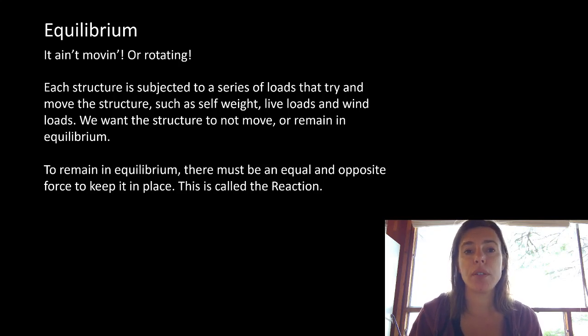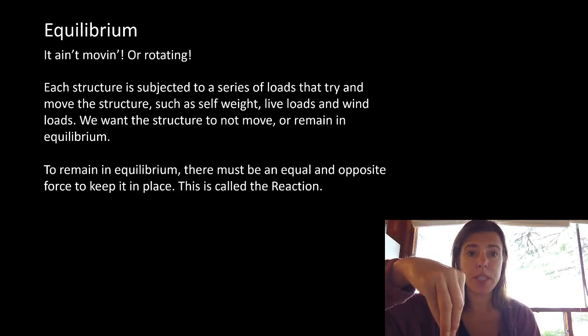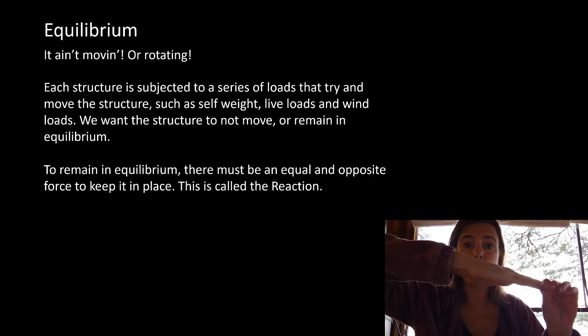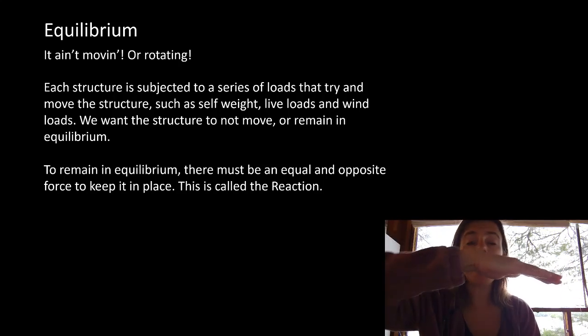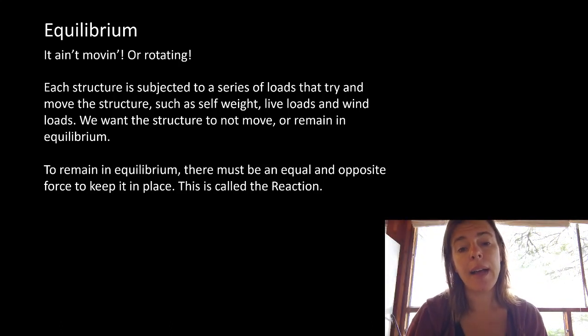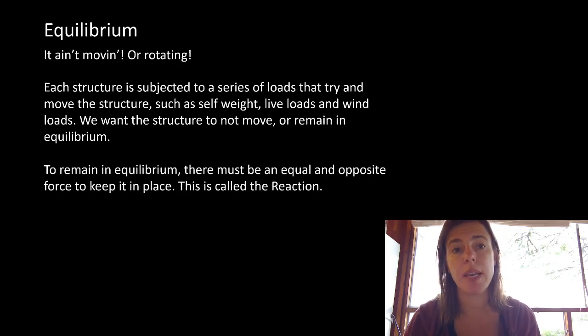We want the structure not to move or remain in equilibrium, so there needs to be an equal and opposite force that's keeping me in place, or a reaction. So we need to know that every system we talk about in this course, for every load that is applied to it, has a reaction. So its own self-weight, trying to push it down into the ground, we need something to push up to resist it. If its own self-weight is trying to cause it to tip over, we need some sort of couple or moment reaction to keep that from happening. So everything is going to need to have a reaction to stop this movement or to keep the system in equilibrium.